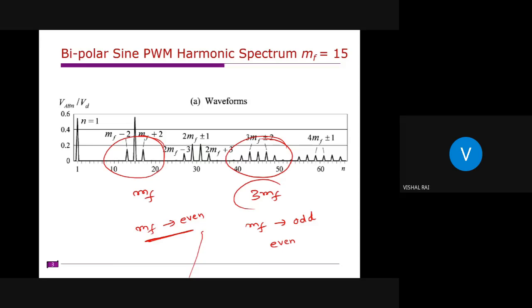So we never completely eliminate all the harmonics, right? Some harmonics will be present, based on the spectrum. When comparing odd order and even order harmonics, even order harmonics are more dangerous, because even order harmonics will normally induce some DC offset.